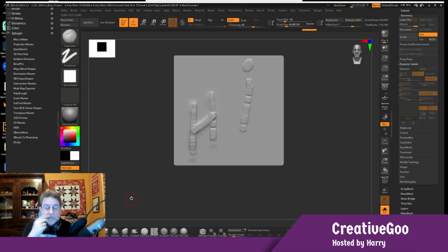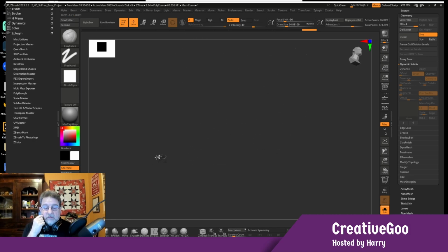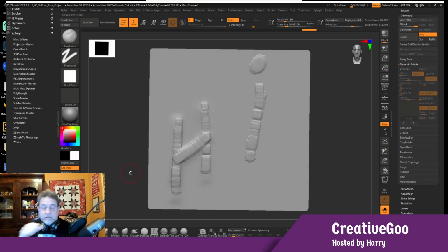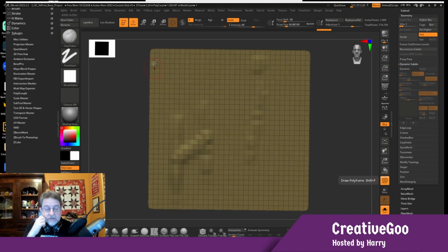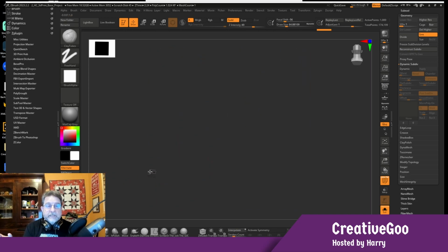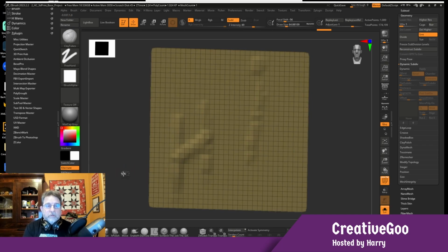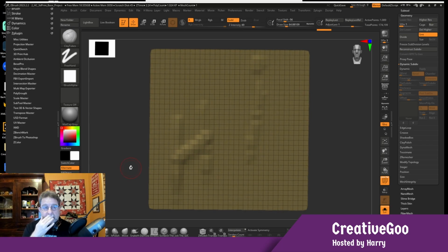Right? I should be able to print that. The problem is there's no other side, right? So on the computer, I can work in 2 dimensions. If I lower and show you the points, there are 4 points that make up each square. In space, they're on a flat plane. So there's an X, Y, there's no Z, there's no thickness here. So this is not printable. It would be a division by 0, right?